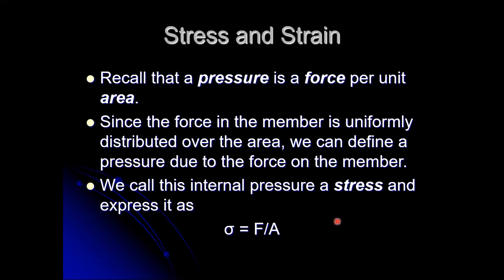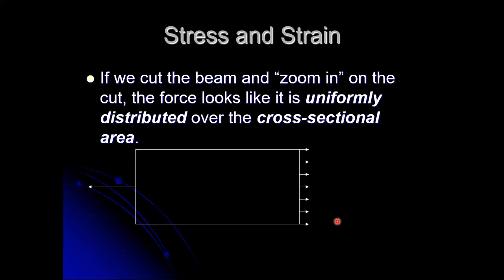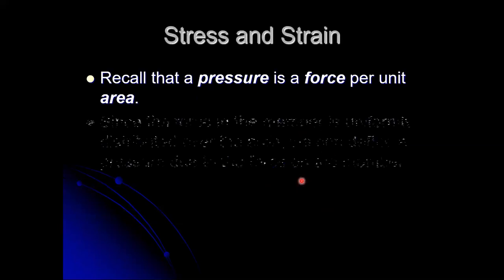So that's our stress. We call it normal because it's perpendicular to the surface. If we go back to this picture here, the stress is viewed as this distributed force. And because that distributed force is perpendicular to the area, we call it normal. Normal is a math way of saying perpendicular without using so many syllables. We save a couple of them. But normal means perpendicular. So normal stress is at 90 degrees to the surface.